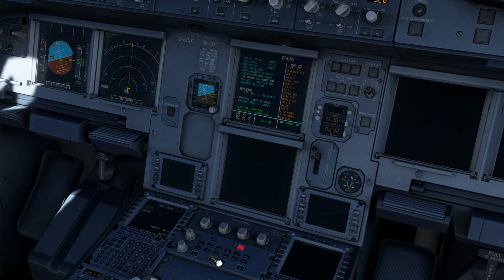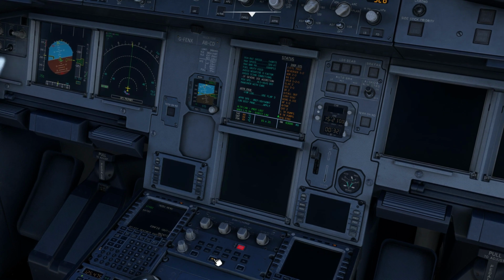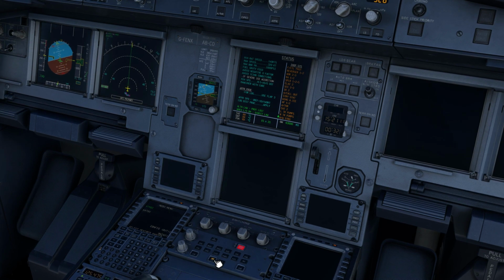Fuel gravity feed. Avoid negative G factor. Avoid severe icing conditions. If severe ice accretion, min speed, VLS plus 10, or green dot. Maneuver with care. We are unlikely to enter icing conditions. Approach procedure. For landing, use flap 3. Approach speed, VREF plus 10, 140 knots. Landing distance procedure. Apply. We are in alternate law, protections lost. When landing gear down, we will enter direct law.